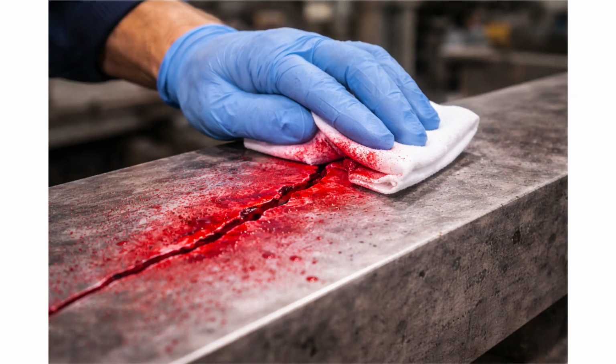Step 4. Excess penetrant removal. After the dwell time is complete, we need to remove all the excess penetrant from the surface while leaving the penetrant that has seeped into defects alone. This is a delicate balance. There are 3 main removal methods: water washable. Some penetrants are formulated to be washed away with plain water. These are convenient but require care not to overwash. Post-emulsifiable. These penetrants require a separate emulsifier chemical to be applied first, which makes them water washable. This gives more control over the removal process.